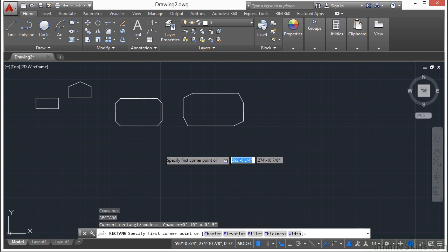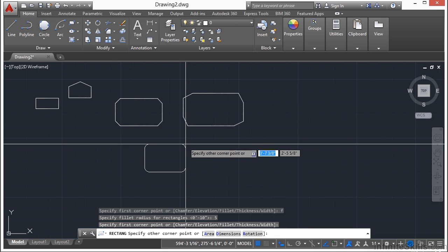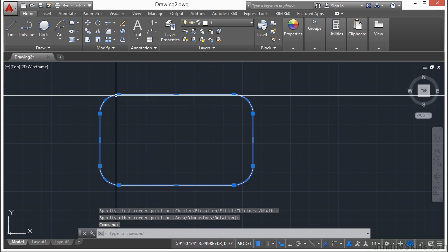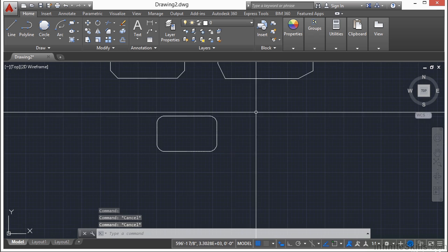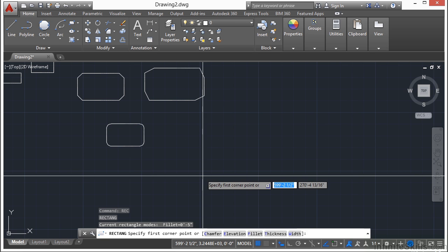Now the fillet option for the rectangle command works almost identically. So you start the rectangle command, type in F for fillet, press return, and then you enter in a value. I'm going to enter in 5 again, press return. So instead of the notched corners, corners are going to be round. And it has a radius of 5 units. So that's the fillet. It's very simple, and it makes a nice little shape. Rectangles are simple polygons, but you can get pretty fancy when drawing with them.